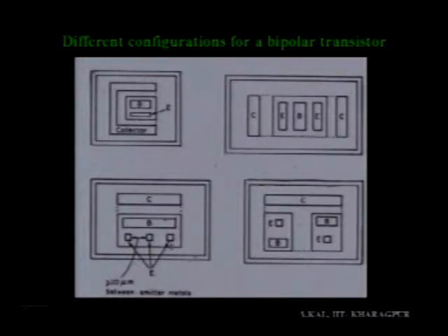That means in one island you are getting 3 transistors here. Similarly here in one island you are getting 2 transistors. The difference between the third and fourth structures is that here 2 bases are diffused. Here you see this is one base and this is another base, but here in one base 3 emitters are fabricated. Here base and emitters are different, but the collector is common, similar to the earlier common collector transistors. So these 4 configurations, you can choose any of them depending on your applications.